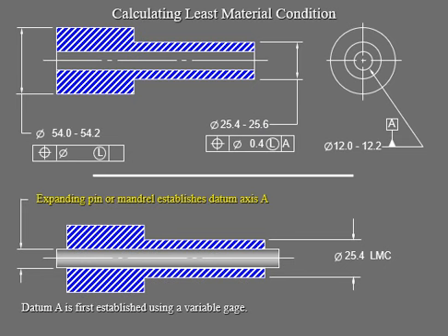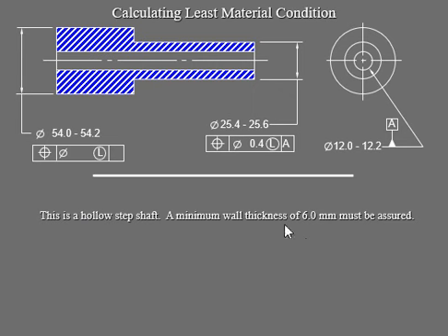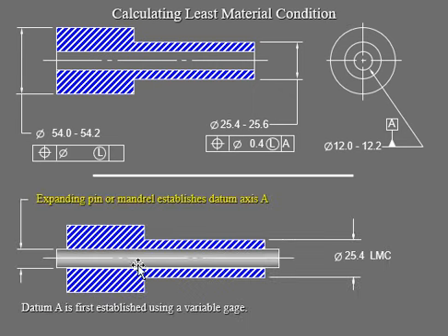Now we're going to expand the pin. You can see the shaft is going to come in right there, which we talked about here. This is for the shaft. This is the hole, so you can't see it. Now we're going to get into the shaft. Your pin is going to go straight in. Your pin is a shaft anyway. Your mandrel, that's going to establish your datum A right there, which is going in this direction in the hole, of course.